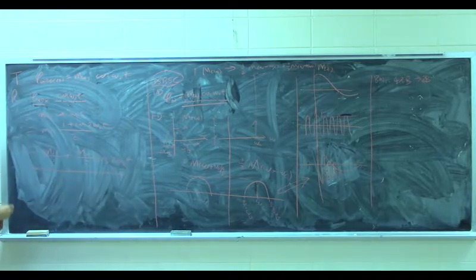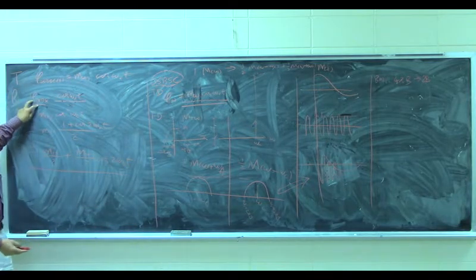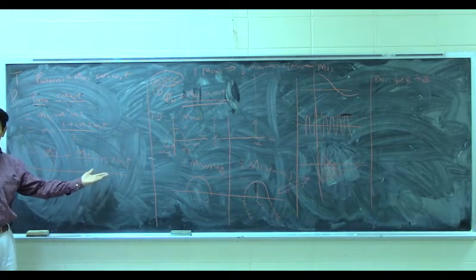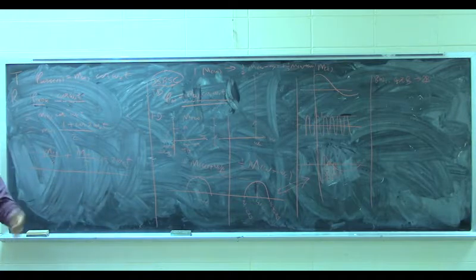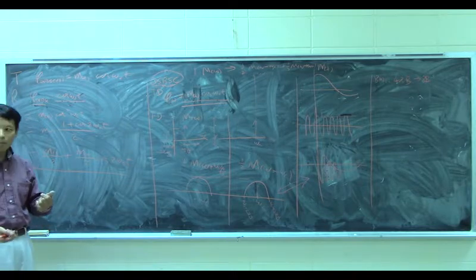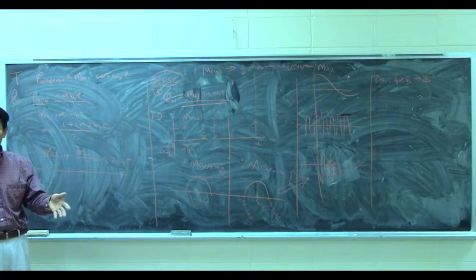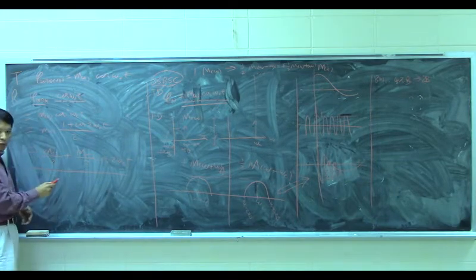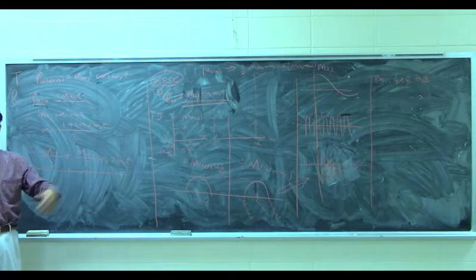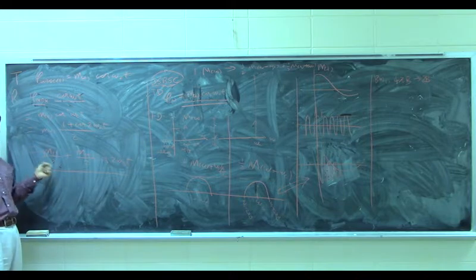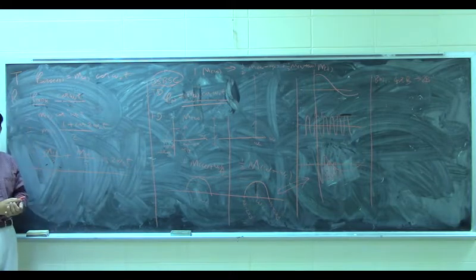So this is our received signal multiplied by the carrier signal. That is what we have. Now let's recall what we want at the receiver. We want the original baseband signal, which is m(t). But what we have here is half m(t). Oh, that is okay, right? We just multiply by 2. That is only the amplitude, the power. So that's fine. The information is still here.